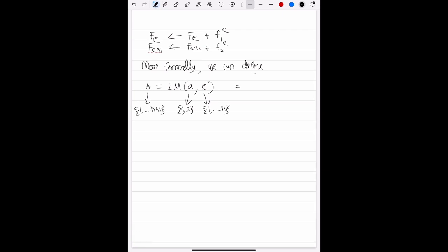So this relation, the location matrix, can be given by is equal to E if A is equal to 1 and is equal to E plus 1 if A is equal to 2. Now how did I get this? We know that if you consider element E, that element E has two local nodes, node number 1 and node number 2, whereas globally the two nodes are node number E and node number E plus 1. And hence node 1 is mapped to node E globally, whereas node 2, a local node number, is mapped to node number E plus 1 in terms of the global node numbers.